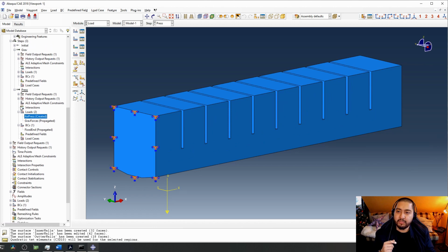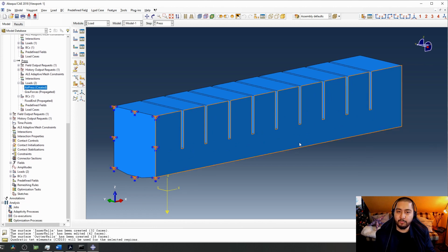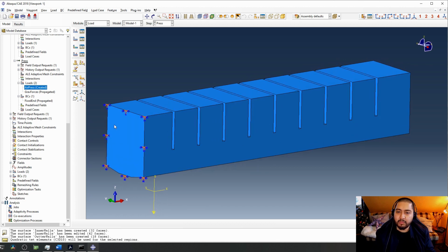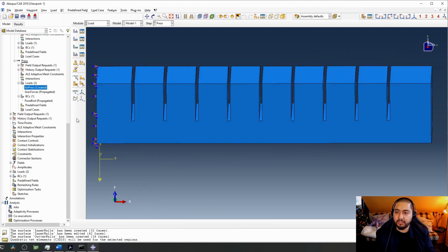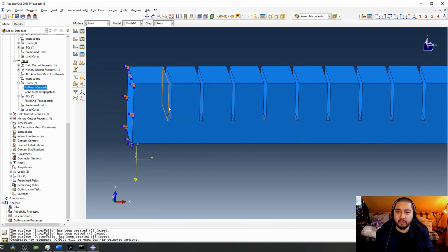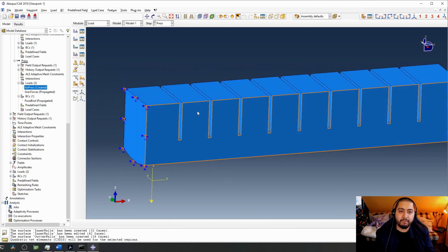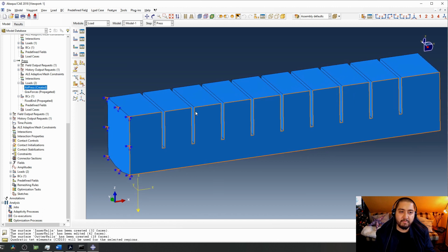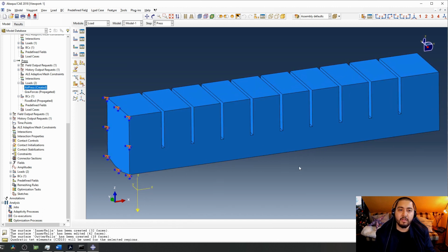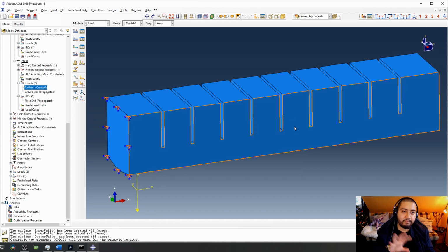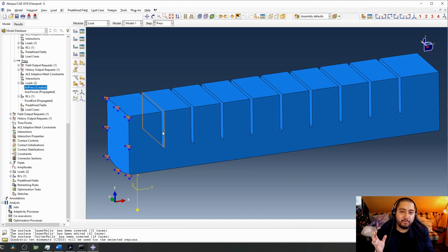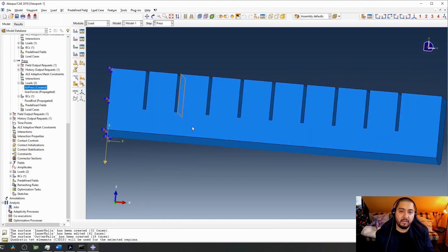And that was most of the complicated things of the simulation to set it up. What we need to do as well is to create interaction. Interaction contact is in between these faces, because if you already have tested or investigated this soft pneumatic actuator a little bit, when they expand, usually these outer walls expand as well, because the air expands on the inside, and every outer wall is obviously expanded to the outside. So probably they are going to have contact when they are highly expanded.